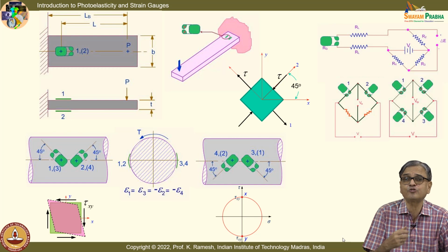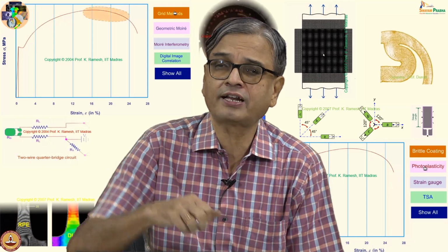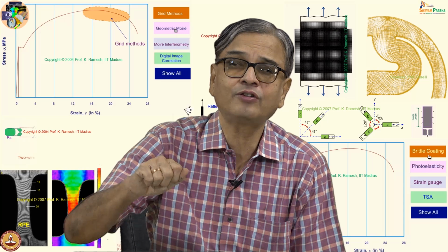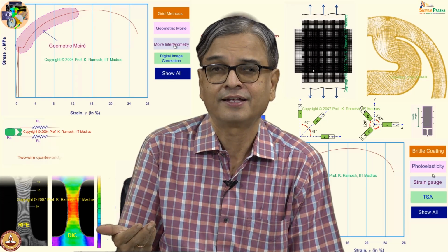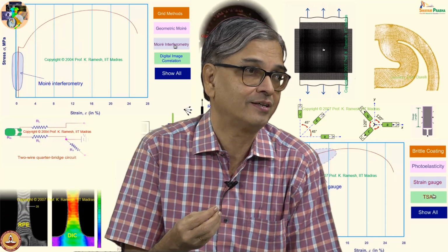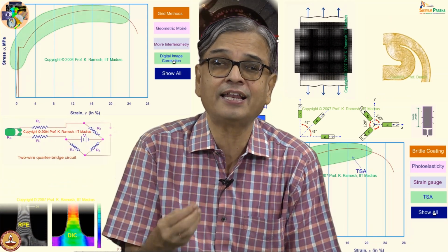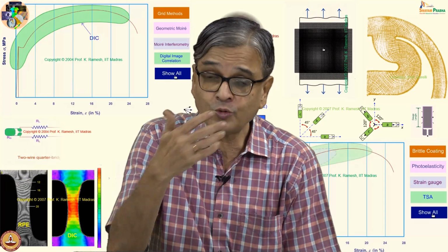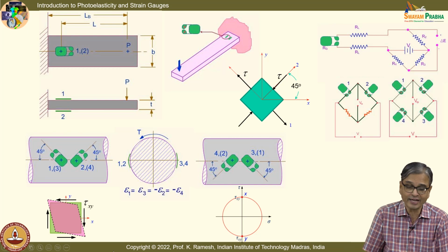So if my interest is to find out torque, I said that you have to use a torque wrench when you want to tighten the bolt. So when I want to have a torque wrench, I should have a system to measure the torque and give you that as a reading. So there are many instances where you have to find out the torque. So it is a transducer application. Your intention is to find out the torque applied. So you design a mechanical element, spring element, in which you place more than one strain gauge and connect them appropriately so that you amplify the signal. So I can make a torque wrench using this as a strain sensing element, and I can amplify my signal.